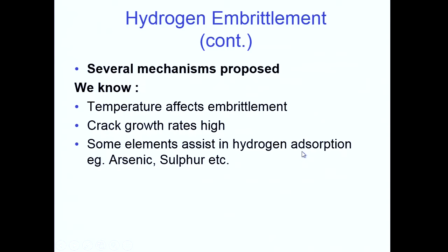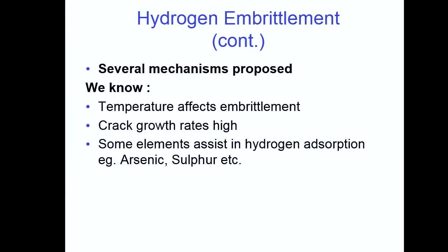And we are talking about absorption of hydrogen as hydrogen atoms. So we're not talking about H+, which is actually a proton and doesn't exist, but you might then decide that it's H3O+, a hydronium ion. We're not talking about that. Inside the metal, we're talking about hydrogen atoms migrating. We're not talking about hydrogen molecules. Okay, they're bigger and slower. We're talking about hydrogen atoms and not charged species only.